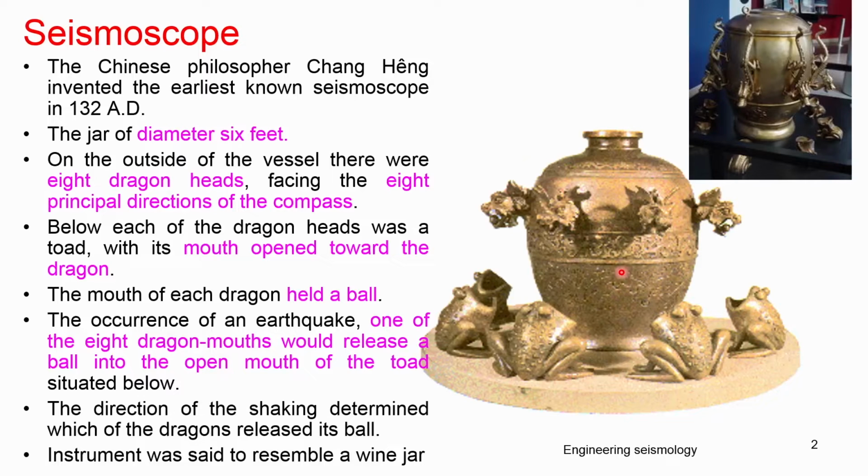As you know, in the Sumatra earthquake of 2004, the tsunami reached the Chennai and east coast after about 2.5 hours, which indicates that you have sufficient time to move the people. The waveform may reach very fast, as the P wave travels close to 5-7 kilometers per second and the S wave 3-4 kilometers per second. But the tsunami wave, as we discussed during earthquake hazard, travels at a much lower speed.